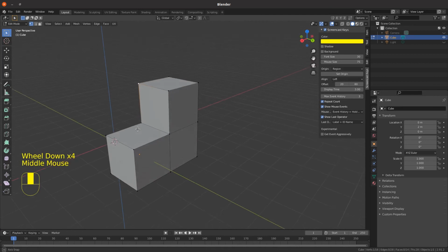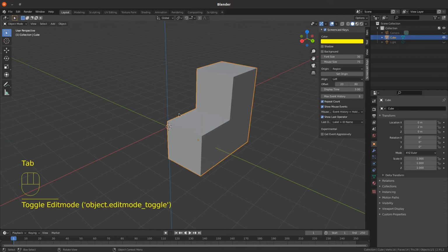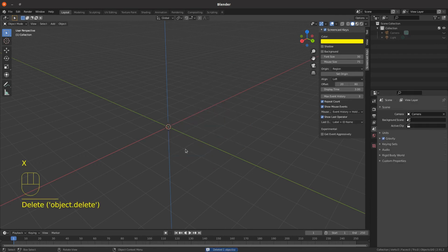But that's the basics, very quickly, of edges, faces and vertices. What I'm just going to show you is I'll delete the cube that we've just turned into effectively an L shape almost. We'll delete that by pressing X in object mode and deleting the object. And I'm going to add a cylinder.